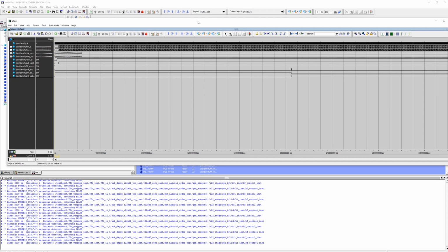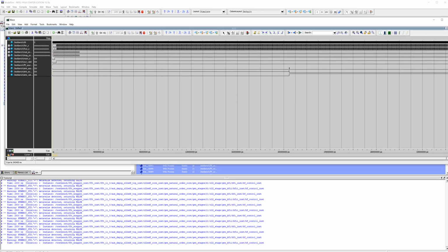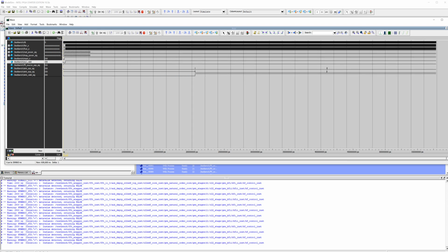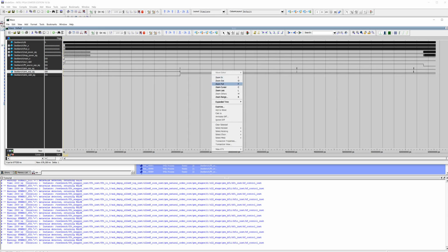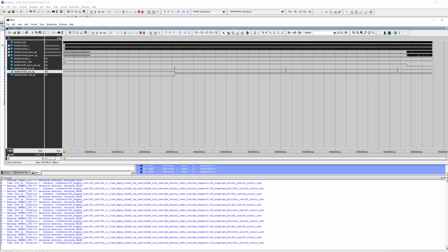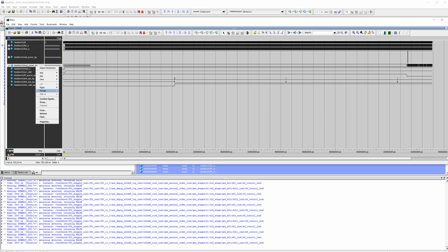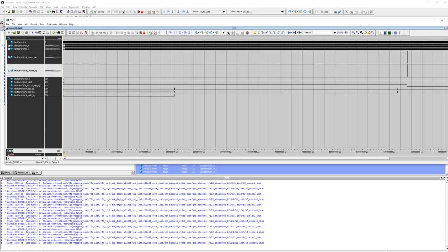So here we are back in ModelSim. Now we have 25-bit signals for the output of the FFT, so that should capture the true output of the FFT. So we're just waiting for those signals to come out. Keep hitting zoom full. So there we go. The signal is starting to come out of the FFT. So I'll right click and go to Format, Analog Automatic, and I'll do the same thing for the imaginary output. And you can see that we have a spike.